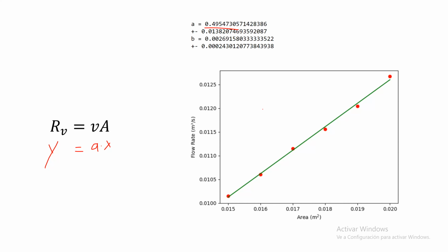This can be for a number of reasons. First of all, velocity is not exactly another constant. As you saw previously, it's another variable. All of these values depend on each other. So therefore, velocity cannot be considered constant. Second of all, as I said previously, air is not an ideal fluid. So therefore, we shouldn't assume that these formulas will apply perfectly to it. And third of all, there could be any turbulence or a small error that we made that will change the flow rate. So sadly, we didn't get a static flow rate, but at least we proved that some of the derivations agree with experiments, even if it isn't an ideal fluid we experiment in.